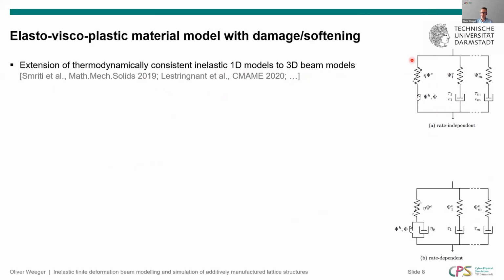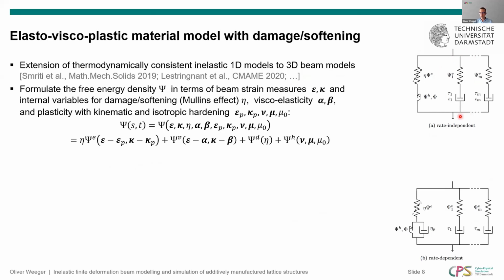So essentially, you can imagine the whole material model using this mass spring damper analogy, like for instance a generalized Maxwell model where you have some springs and some dashpots which are in series, and then in parallel you have different elements, where here this would be the plastic element. And now for each of these branches or in total, you have a strain energy, which is the psi over here, or total internal energy function.